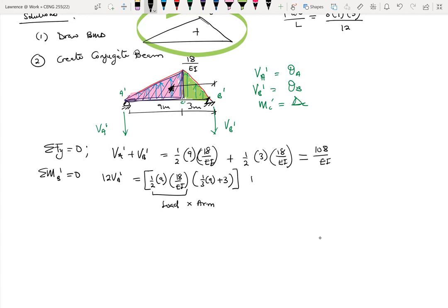Okay. Then the right-hand side, again, the area is the same, nothing changes. So this is the reason why I divided the area into 2 when summing up forces, because it also helps me when dealing with the moments. Okay. So again, here is the load. Now times the moment arm. So the moment arm here will be 2/3 of 3 meters.